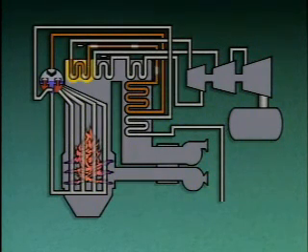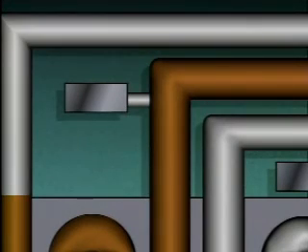The secondary superheater raises the temperature of the steam again. The secondary superheater is usually located closer to the boiler furnace so that it's exposed to higher temperatures. The secondary superheater may be either a convection superheater or, as in this case, a radiant superheater. This boiler has an attemperator, or desuperheater, located between the primary and secondary superheaters. The desuperheater keeps the steam from becoming so hot that it damages the superheater tubes.